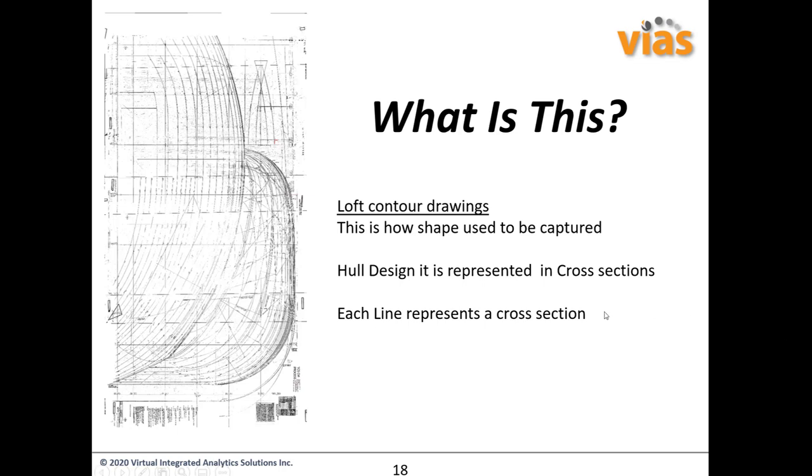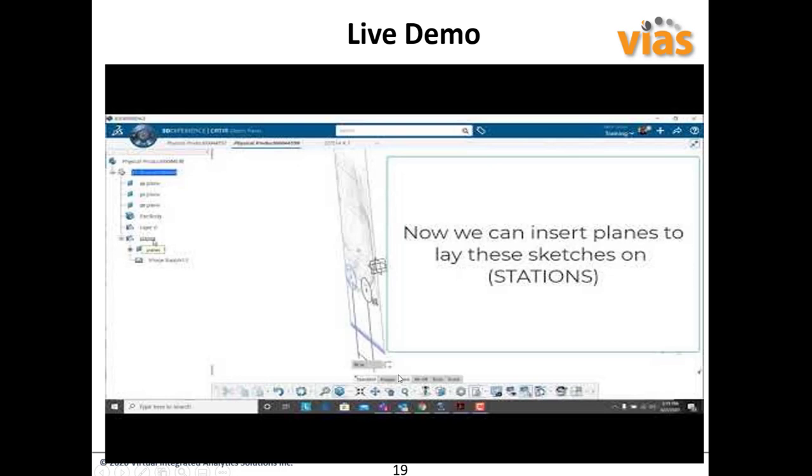If you can see a Mylar, or what they call the Mylar, they would draw this out and print it on plastic to make it more stable over the length of the Mylar plastic. And then we go ahead and we bring in the picture of it into Catia, again, like I did with the Corvette. And you can put these on station. So usually an aircraft print would go on station 0, or you'd put it in front of station 0 of it.